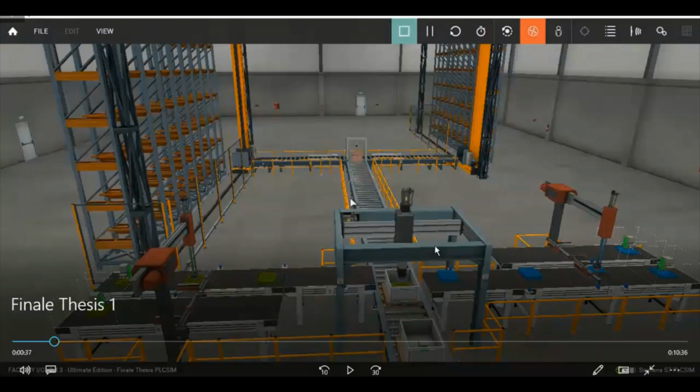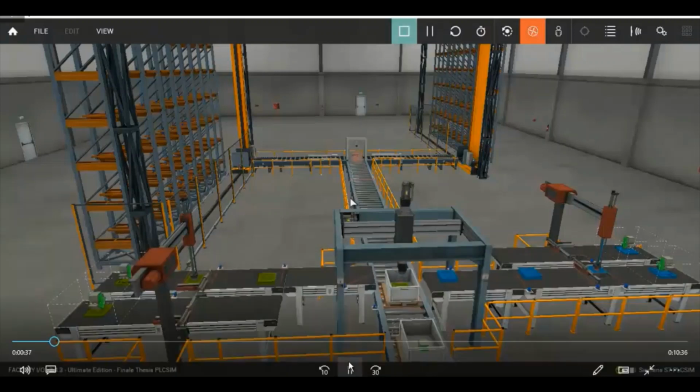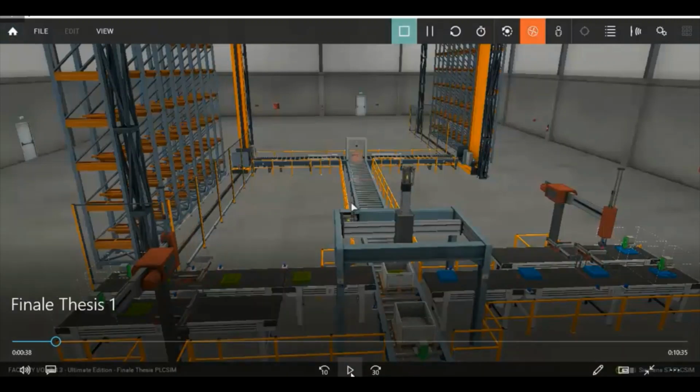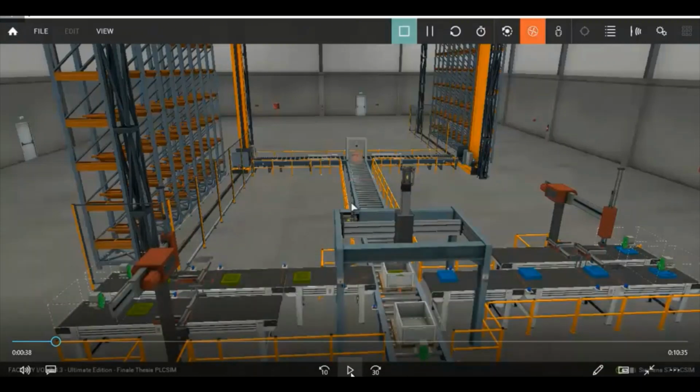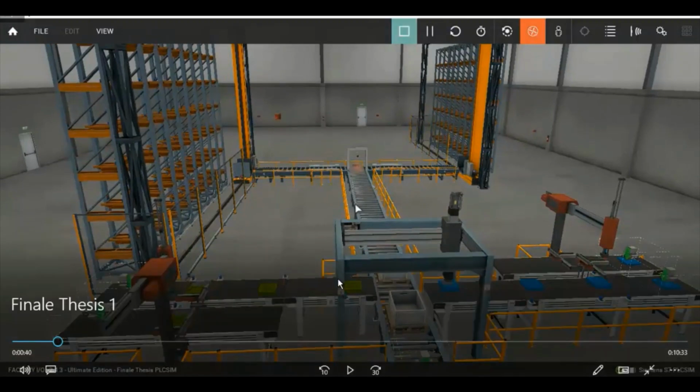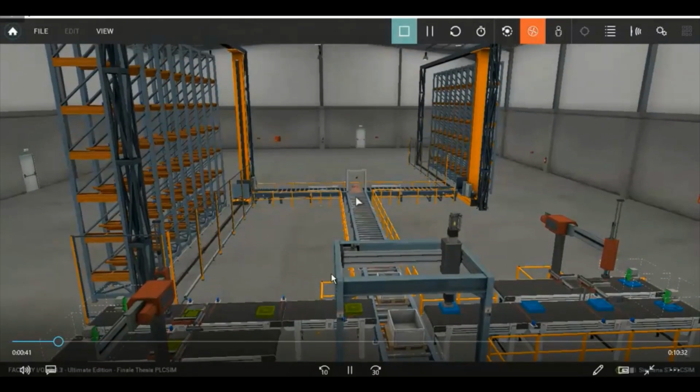If the pick and place is stopped, then this conveyor is stopping and also this. And if this conveyor and this are not working, obviously these pieces are not going to be moving, so this machine is not going to pick it and place it. It's all related. And I think that's the hardest part in ladder programming, it all needs to be related, and there you start to see a lot of inputs and outputs in the process, and it sometimes confuses you.